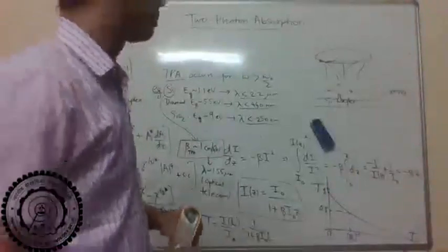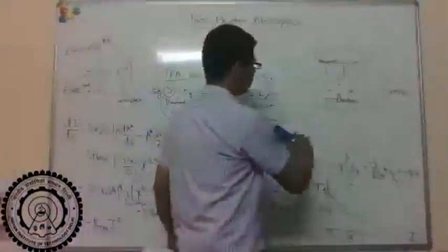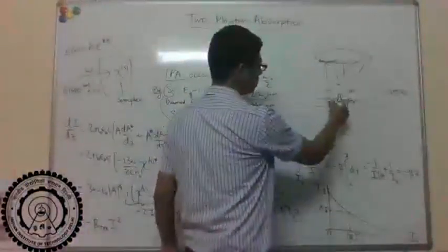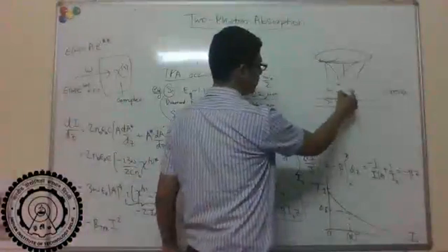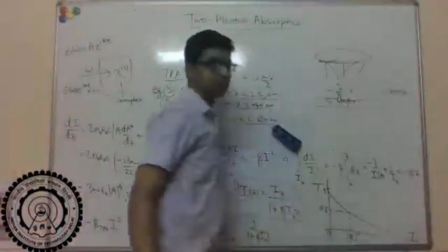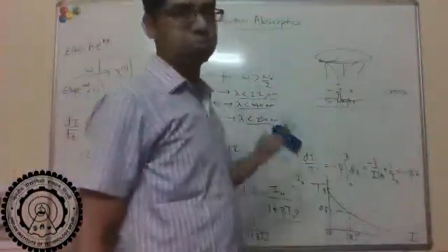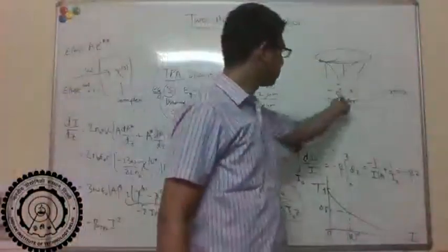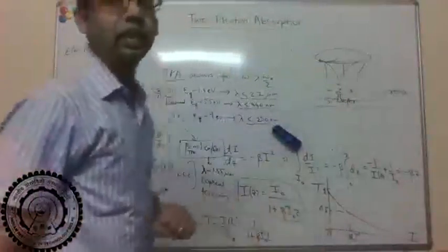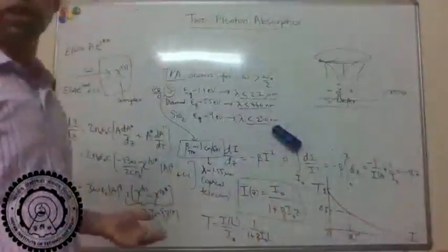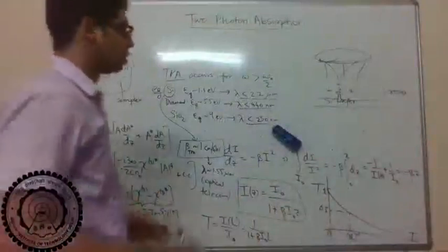Yes, sir. So in the usual linear photolithography case, the minimum size you can get is of the order of the wavelength. So let's say if I'm using some visible wavelength, 600 nanometers, and that's the smallest size I can get. But if I want to make smaller, then I have to think of something more.